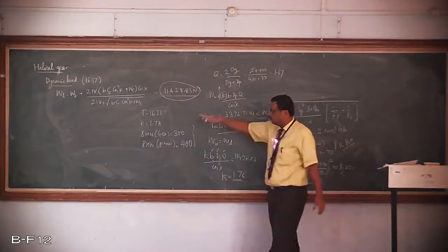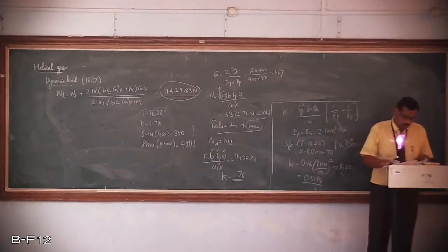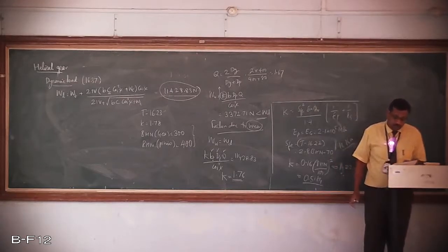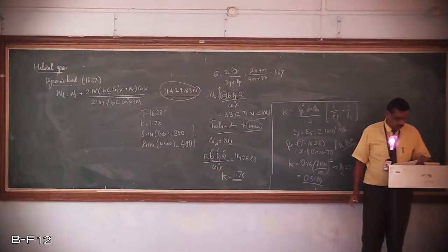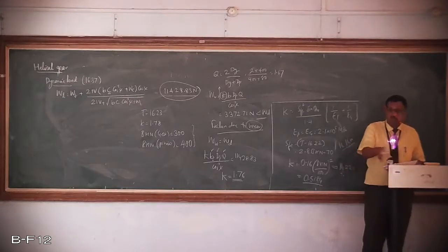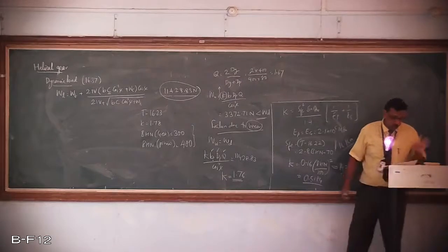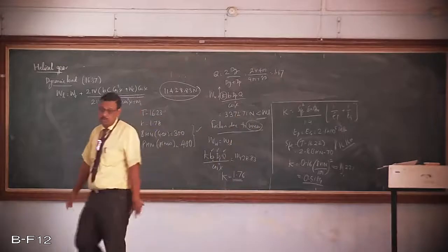Now refer to table number 16.23, which is the table for the load stress factor. Corresponding to 20 degrees, go on searching where the value of 1.78 is. They are given material steel, cast iron. Check for the material, both are steel only. You may get 1.7 in other categories also. So for 1.78 for steel and steel, you get gear as 300 BHN and pinion as 400, this is what we are suggesting, and this is how you have to complete the design of helical gears.